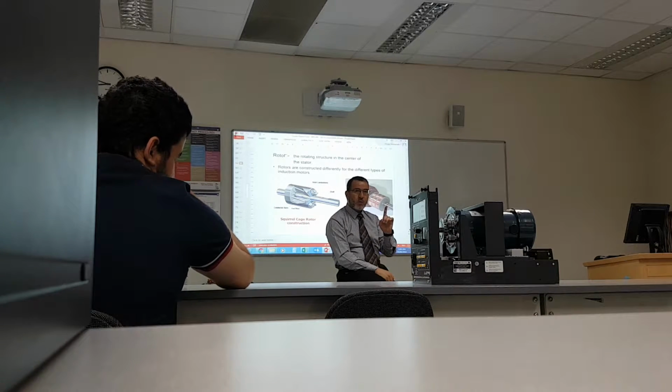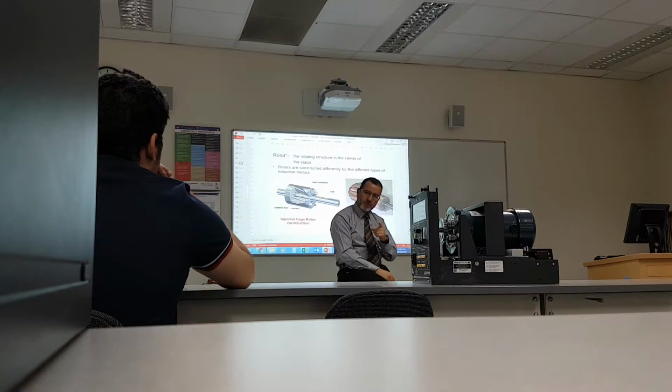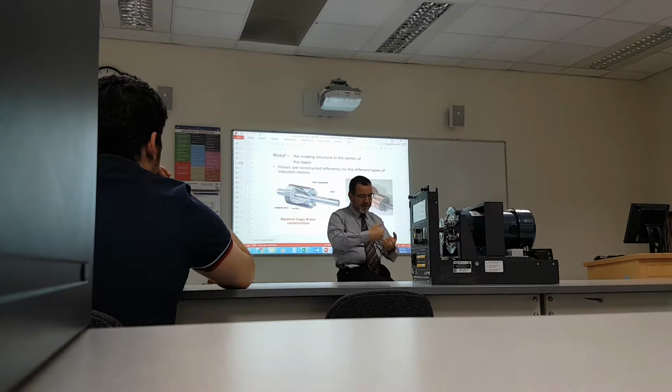Now, when the motor is not loaded, they are perfectly matched, 1 to 1. When you start increasing the load, it's like a rubber band between the poles that is being stretched. You increase the load, it stretches a little bit, so the stator field is a little ahead. Still the same speed, but just stretched a little.